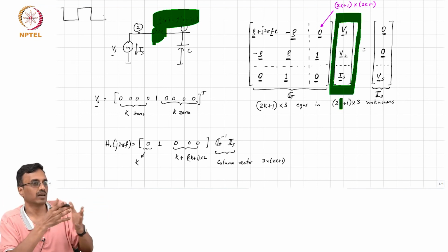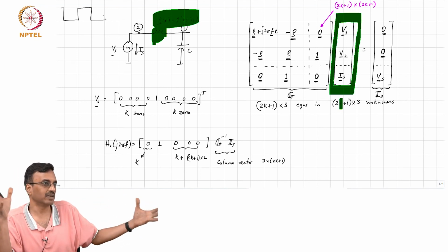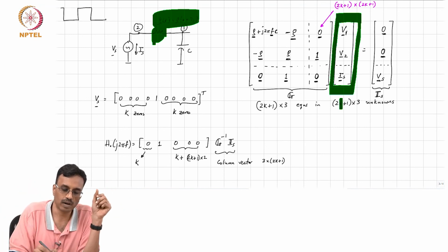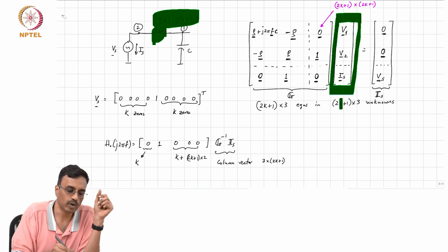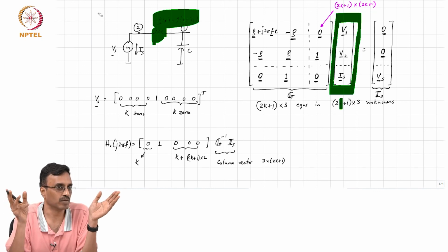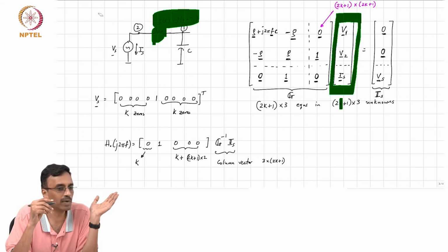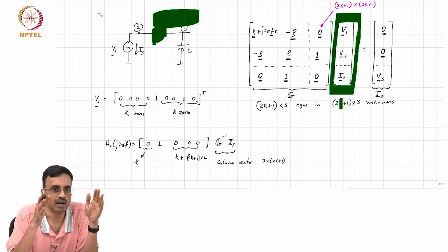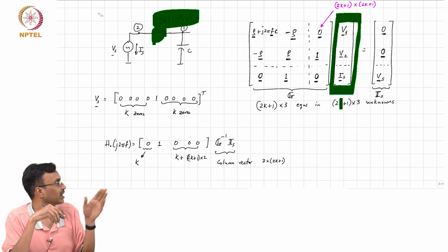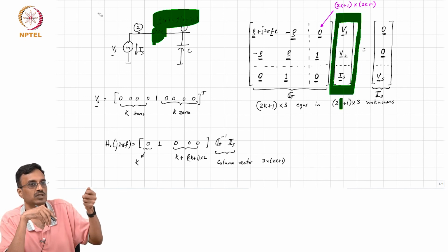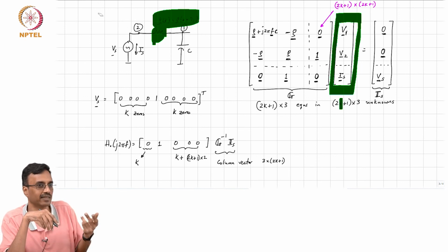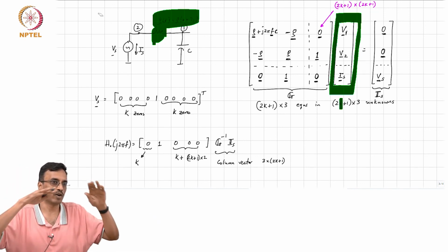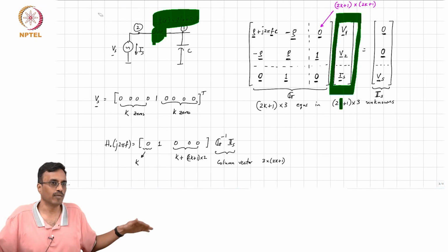And therefore, it stands to reason that you must consider a lot of harmonics of G of t to be able to get a reasonable representation of this stuff. So, it's not uncommon for K to be 1000, 2000. Fortunately, in every physical system you can never turn a switch on or off instantaneously. There will always be some rise time and some fall time, and that basically means that the higher order coefficients are falling off to 0,